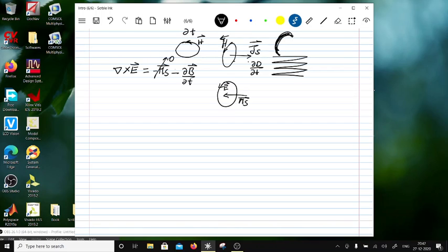So there will be a clockwise loop if this goes inside, opposite to what Js was doing. Ms is doing in the opposite direction. It will be clockwise if there is a magnetic current density, and you know that magnets do not have isolated north and south poles, so you cannot have a magnetic current flow. So it's a fictitious number.